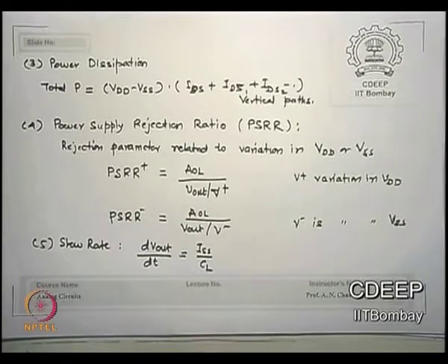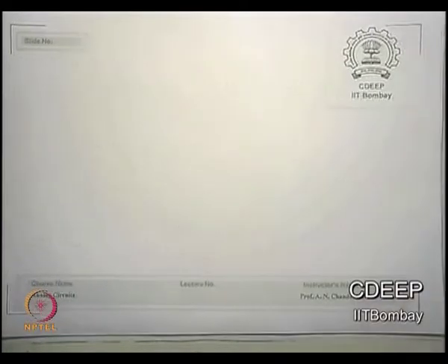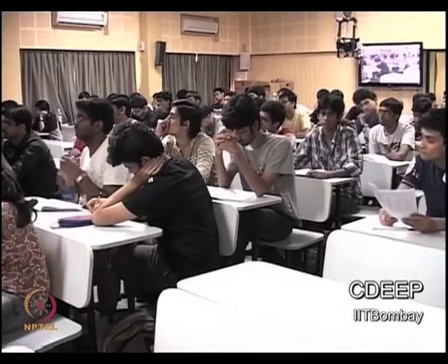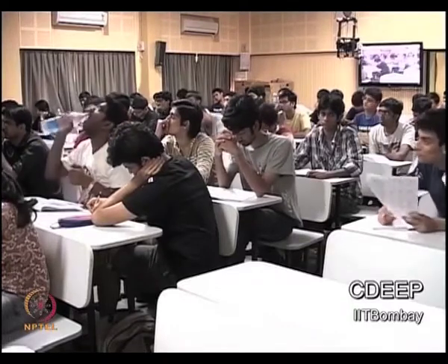Last time I also gave you an example showing that the current ISS is fixed by the requirement from slew rate, the requirement from power and the requirement from the gain. So all three should somehow be matched to everyone's requirement. Okay. There are a few more characteristics, but these are the essential characteristics which everyone must know before we start working on an OPAMP in a lab.